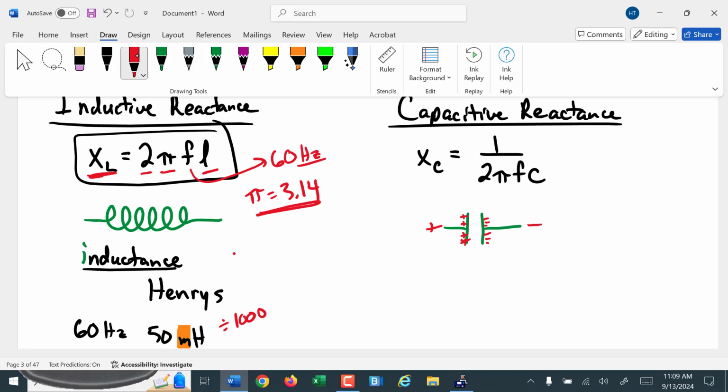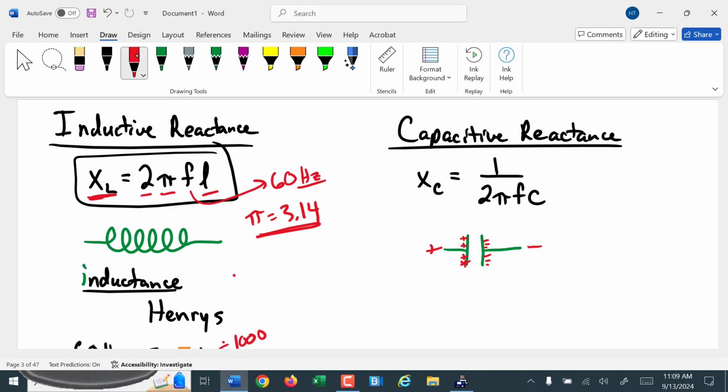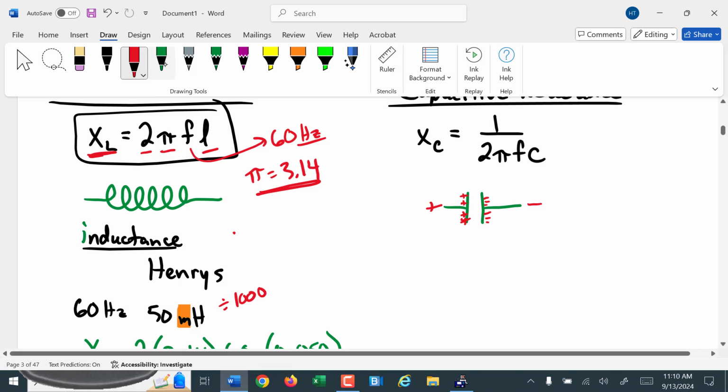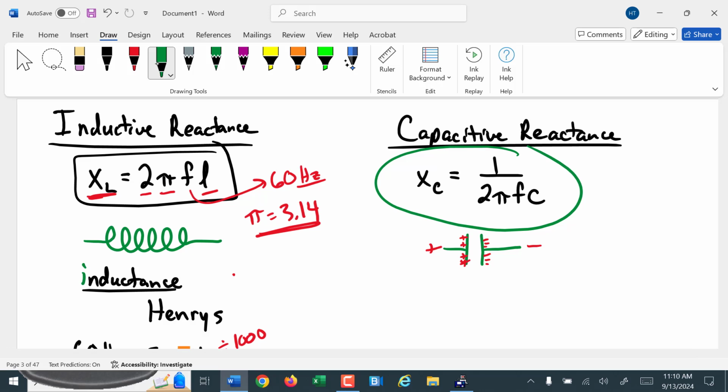So you can actually use it to power a circuit for a very short period of time. Capacitors are usually used to protect against power surges and any little bumps in the power. They're to even out the current in general. So they obviously can have a huge reactance, a huge stoppage in the flow. If this is a DC circuit, a capacitor, once it's charged, has an infinite resistance. No current can flow through it at all. So we're only dealing with an AC circuit here. The capacitive reactance is 1 over 2 times pi times the frequency times the capacitance.